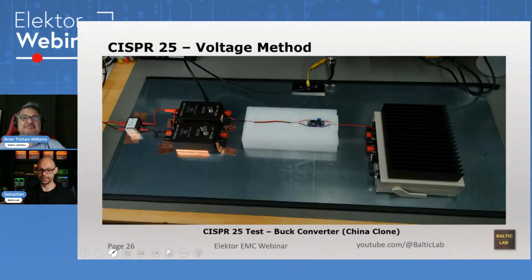Everything looks nice until you figure out that one connector has actually broken off, but due to the close proximity, there's enough capacitive coupling that it appears to be working in general. If it were at lower frequencies, you'd just have a complete air gap and not measure anything. Those are things that surprise me all the time. It actually happens more often than you might think.